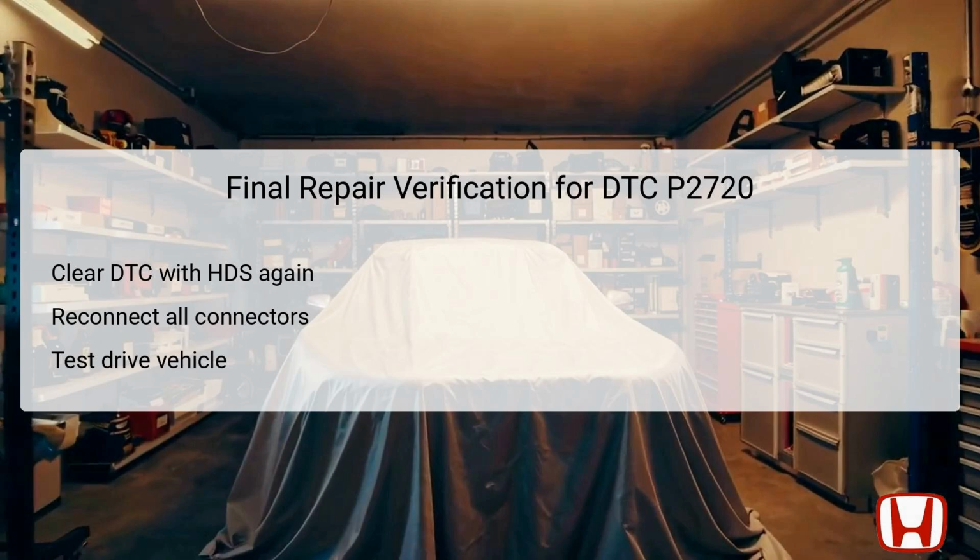Once all repairs associated with DTC P2720 have been completed, a final repair verification is essential to ensure that the issue is fully resolved. The technician should begin by using the HDS to clear the DTCs again, which reinitializes the system post-repair. After clearing the codes, all connectors must be securely reconnected to guarantee that all electrical circuits are intact.